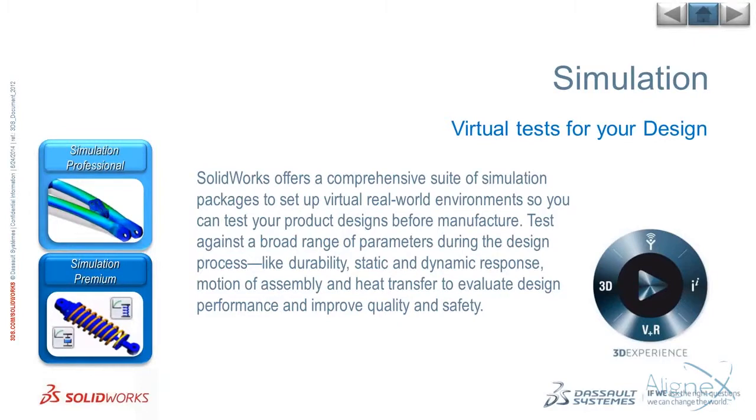We can also run basic motion studies to investigate rigid body dynamics to help us with motor and actuator design. The rigid body motion solver assumes that the bodies are rigid and cannot deform under loading, so they can't change shape under loading. However, the forces are still transferred from body to body.